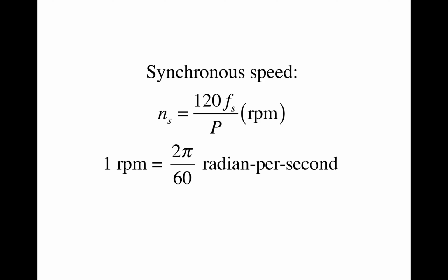The three sinusoids of the current are separated by 120 degrees, or 1/3 of the period, and each sinusoid delivers its maximum at a different time. And the magnetic fields created by the three different current phases combine into a single rotating magnetic field. And we derived the rotational speed of the rotating magnetic field, which is called the synchronous speed.